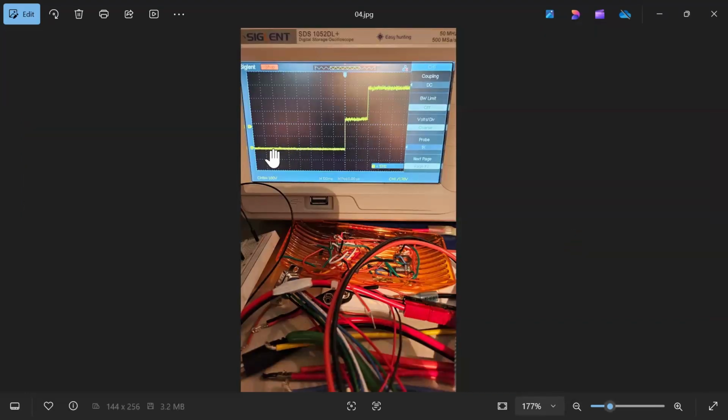And here we see that the whole circuit is off. At this point, the circuit powers up and comes up going through the current limiting resistor. And here the PIC microcontroller starts its timing. Here's 100, here's 200 milliseconds. It turns on the MOSFET transistor, which bypasses the current limiting resistor, and we go to full power. So there's that stair step, right? We're essentially at 50% power, and then 100% power will be delivered to TTL computer 2.